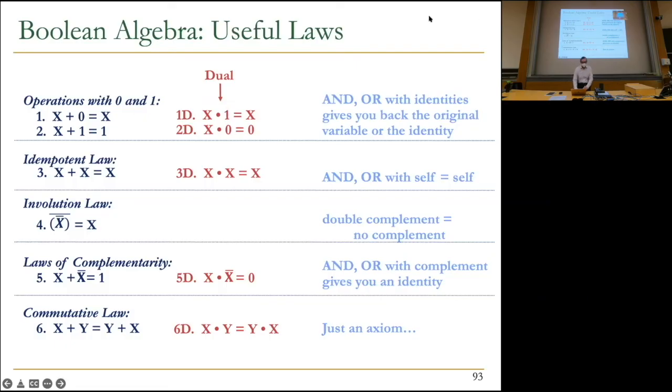This is a simple AND gate, right? Again, you can do it here: x or 1 is 1, because x doesn't matter if one of the inputs is 1 for an OR gate. And if you form the dual of this, you get x and 0, and that's 0. Basically, we could actually get this without thinking. I change this to its dual, change plus to dot, and change 1 to 0, and you get this equation without thinking, because these are the theorems that enable you to operate on equations.